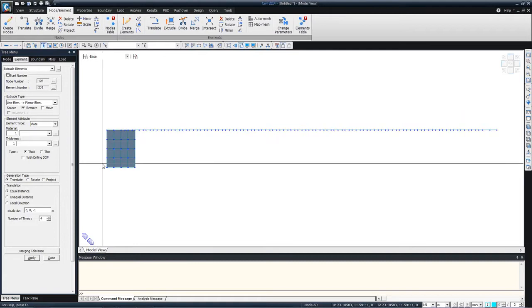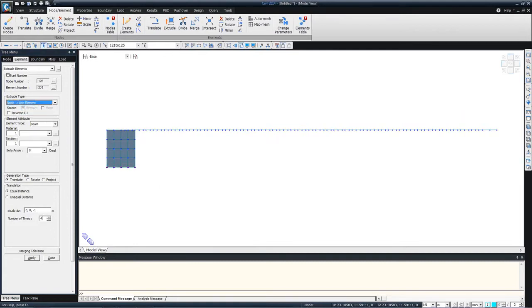So simply copying here and changing this to node to line. Say normally we have the soil profile for the pile at every 1 meter interval. So we know how the subgrade reaction changes at 1 meter intervals from the soil data, because soil structure interaction is very important for integral bridges. We therefore have to consider a good amount of accuracy when assigning the soil springs.